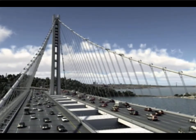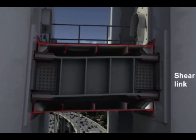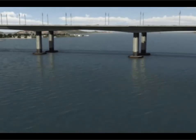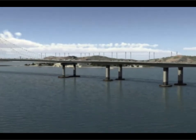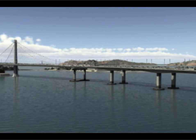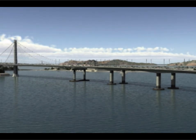On the suspension bridge, the tower and roadways would move independently. The tower's 4 shafts would sway up to about 5 feet, but damage would be confined to steel connecting plates called shear links. The bottom of San Francisco Bay is covered in deep mud, which can amplify ground motion in an earthquake, so piles for the span's piers were driven at an angle to provide more stability. If the design works as planned, damage from a major quake would be limited to a few parts of the span, and the bridge would be reopened to emergency vehicles within hours. This is Henry Fountain of the New York Times.